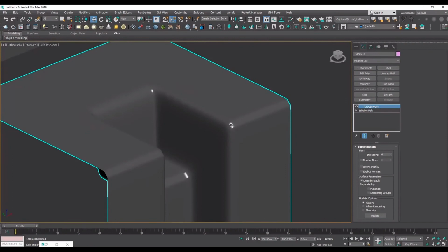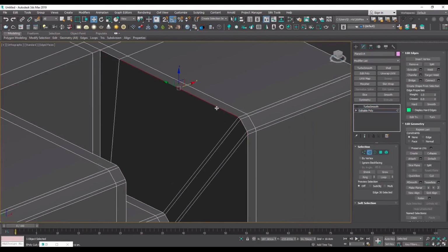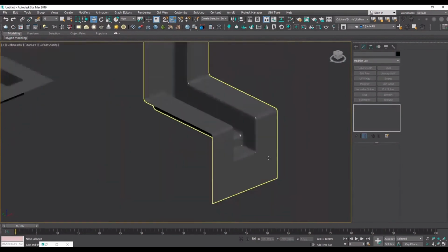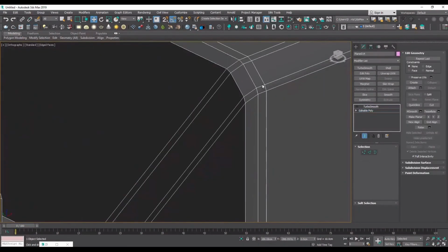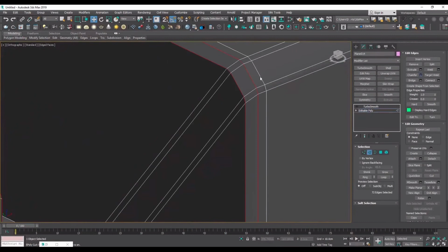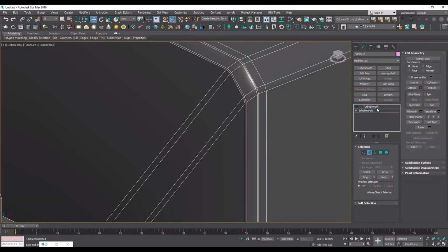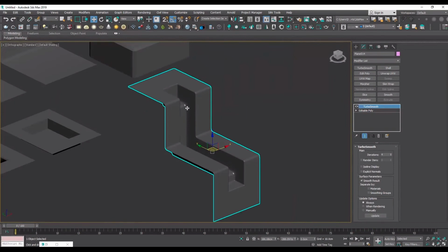Now, I want these parts to have a chamfer, and exactly as I said, I will select these parts and edges and then give them a Chamfer modifier. Also, from the previous examples, now I think we have learned it's good to repeat the Chamfer modifier again to preserve the original chamfer that we did, to preserve the edges even more. And with that, I think the corners are also pretty good.